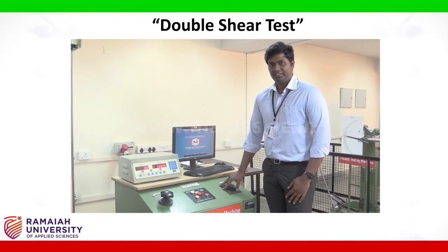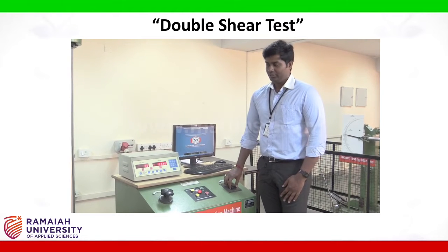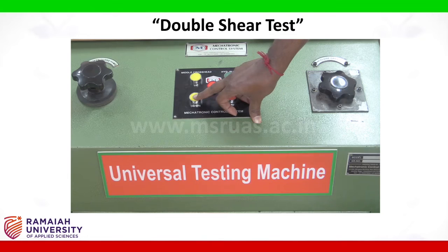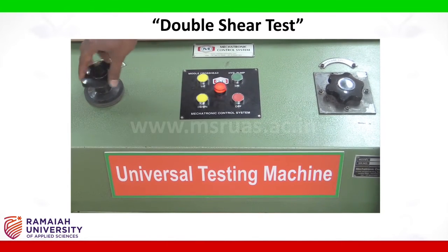After feeding the test data into the mechatronic control system, we need to bring the middle crosshead of the UTM in contact with the top surface of the shear box.